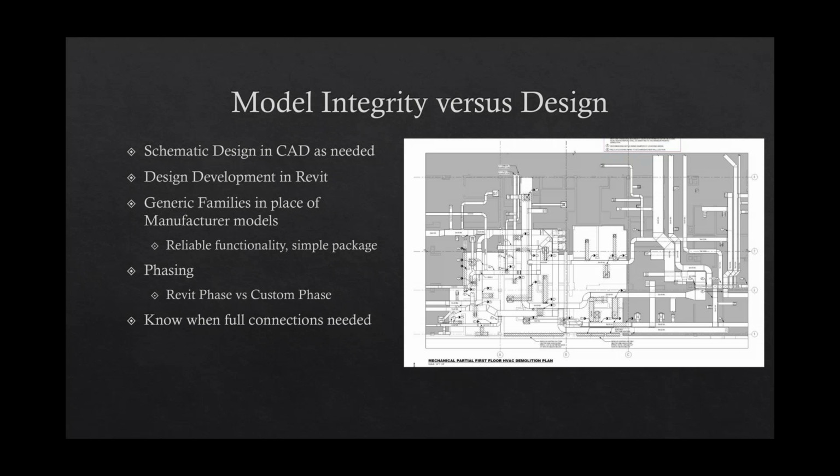But I would say schematic design is the time with the most leeway. It's before things are too set. Things might change considerably anyway going into design development. So I would say schematic design is the time you might consider having somebody do designing in CAD itself. And then during design development, you should really make sure the whole team has brought their things back into Revit. We can also use more generic families in place of manufacturer models where available.